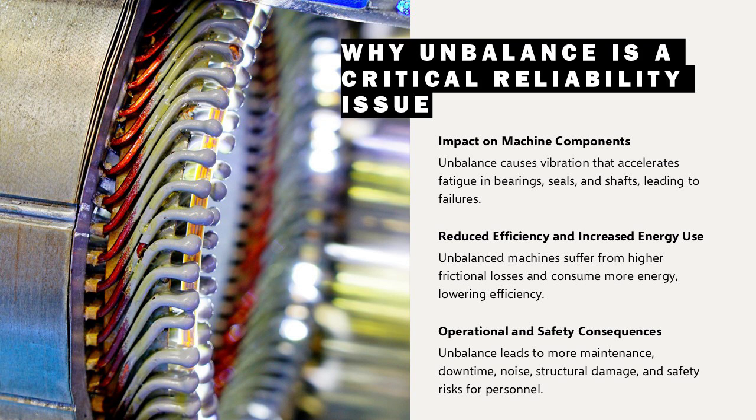From an operational perspective, unbalanced machines require more frequent maintenance interventions, higher spare parts consumption, and increased downtime. In severe cases, unbalance can result in excessive noise, structural damage, or even safety hazards for personnel. For these reasons, unbalance is treated as a primary fault condition in predictive maintenance programs and is typically one of the first issues investigated during vibration analysis.